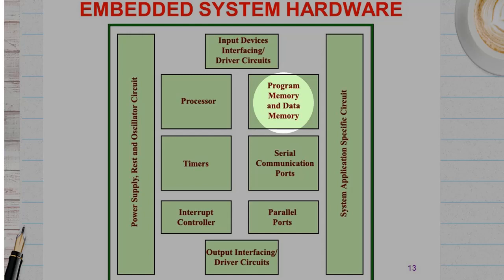This is used to store data by the program itself. Suppose we have a temperature data logger, and it needs to store the data every 1 hour. It means we need to store the data at runtime after the system is started. The system will read temperature and store it in the EEPROM memory. And it will be permanent, and you can retrieve the data later.